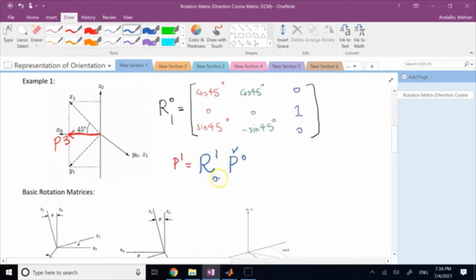Okay, so it is going to go from 0 to 1 because my goal is to go to 1. So 1 is my reference. If I can find this multiplied by that, pre-multiply, that's it. Now, in this example, I already had 1 with respect to 0, but look here, I want 0 with respect to 1. And remember, I said if you want 0 with respect to 1 and you have 1 with respect to 0, just invert that guy.